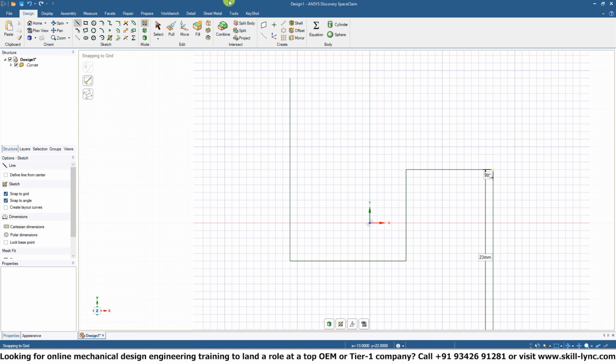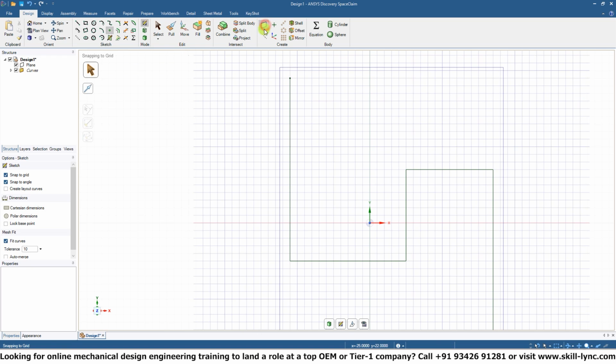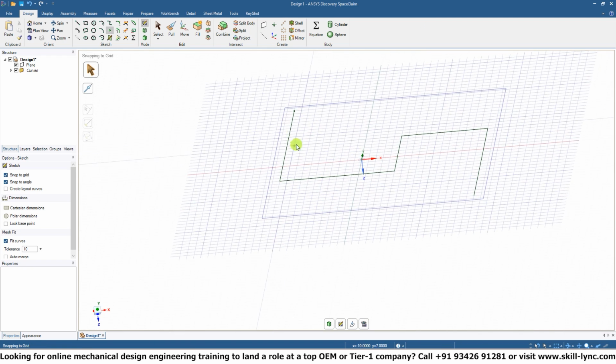Now that we have done that, what's really important is how do we define the cross-sectional surface area of the pipe? We'd have to sketch it on top of this point right here at the start of the sweep path. To do that, we can simply place a point over here at the start, and then we can define a plane right on this point over here.